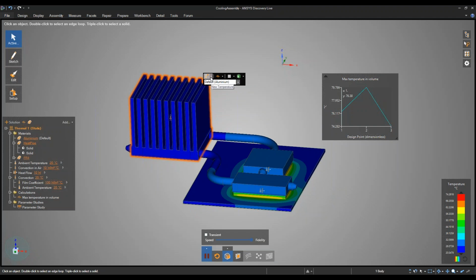Whenever you do that, it comes up with this context menu up here. It'll have all your boundary conditions. Since I selected a body too, I could also change the material, but you can select anything related to bodies at temperature, heat flow, or flux. You can insulate a face. This is all particular to this thermal analysis.